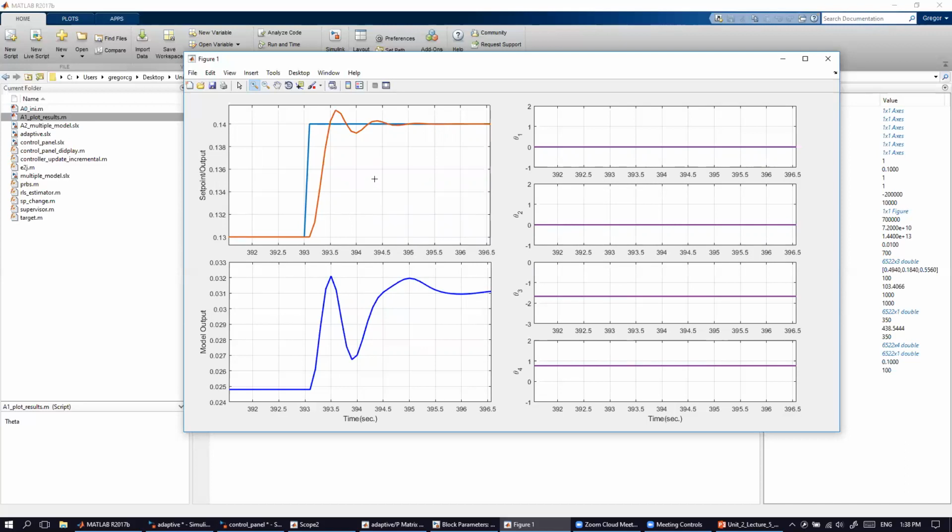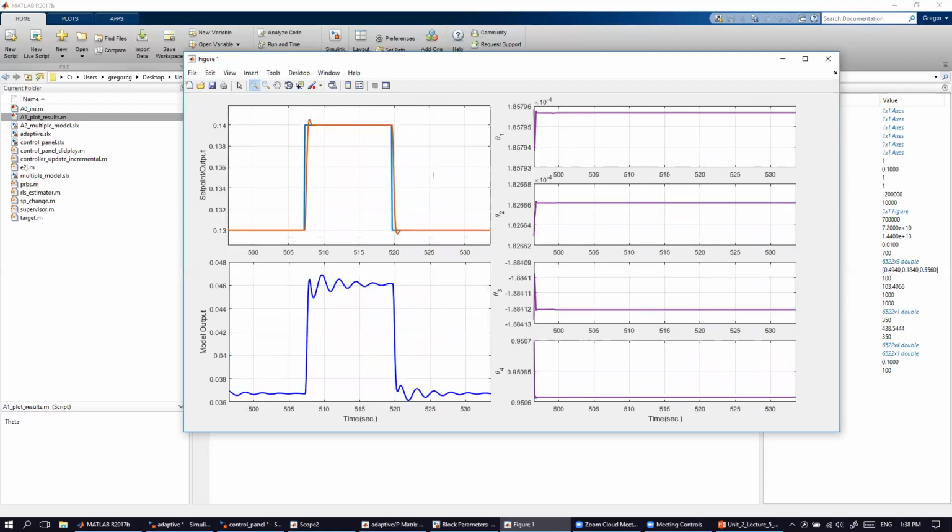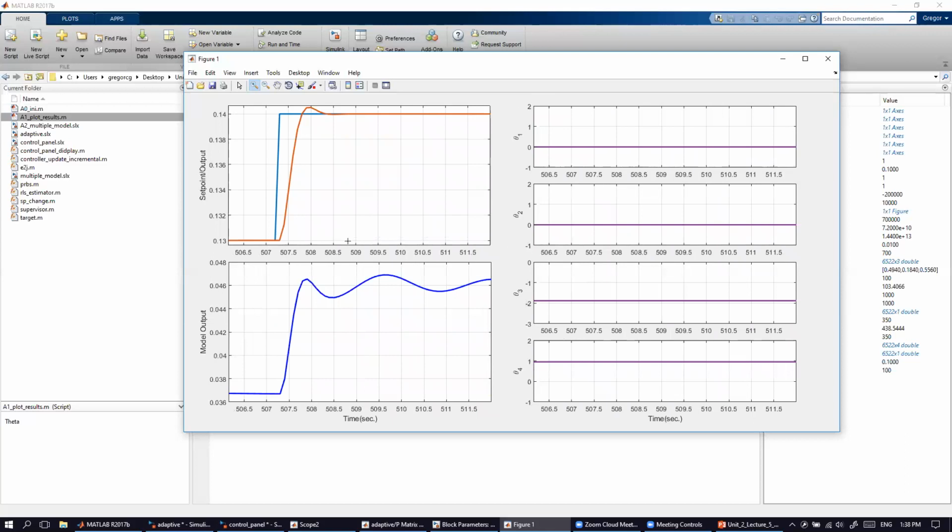Right? And this is not the response that we want. So what we do, we repeat the controller tuning again here, and then we stop the controller tuning and we take a look at the parameter, at the response again. And again, we see now that after the controller has been retuned, we get the response which is the way that we want to have it.